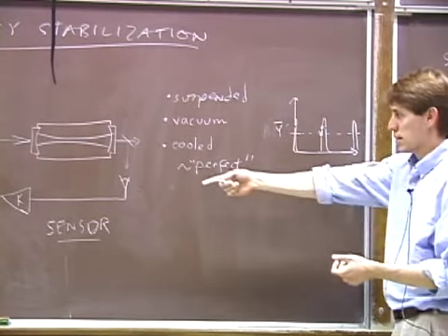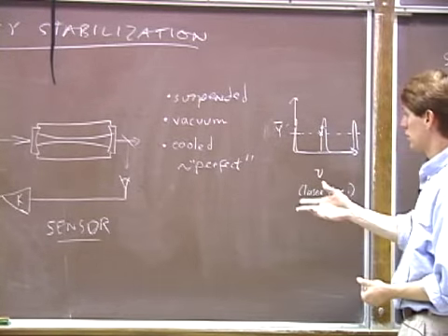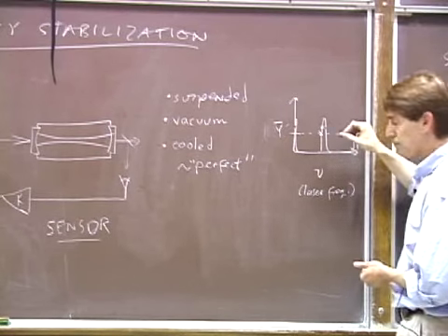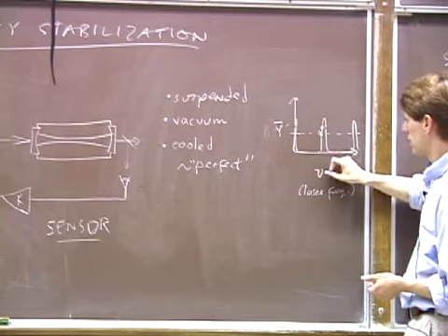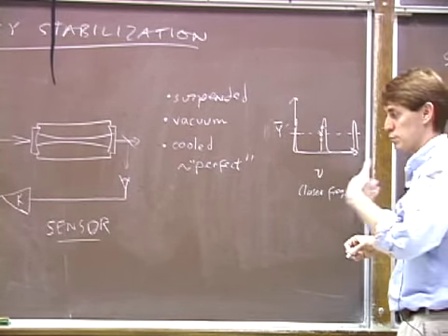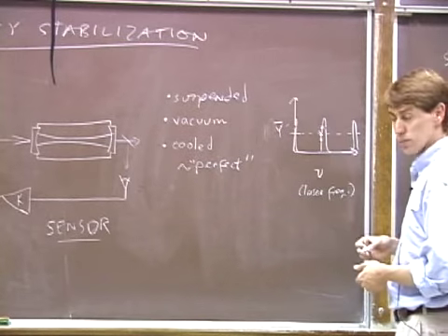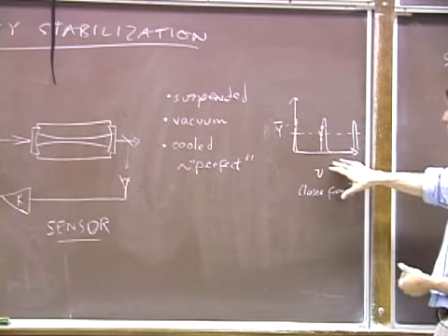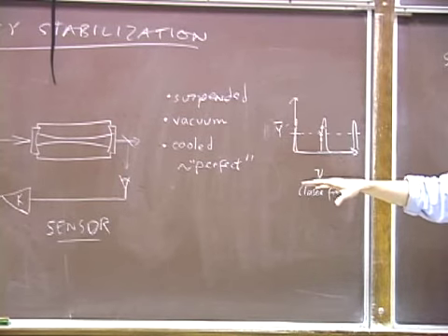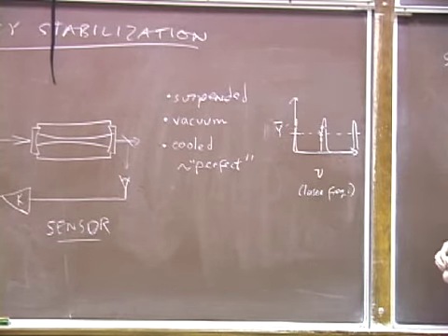The system, okay, it's got a minus sign built into it. It would reduce the laser frequency, push it back down, and bring the system back to its set point. Similarly, if the laser frequency got too small, the power would drop, and the servo would give it a kick and push it back up to its set point. And this is the way laser frequency stabilization was done back in the 70s. This was some of the first techniques that were used.